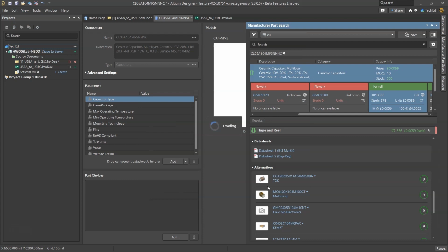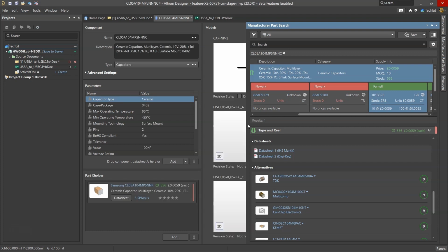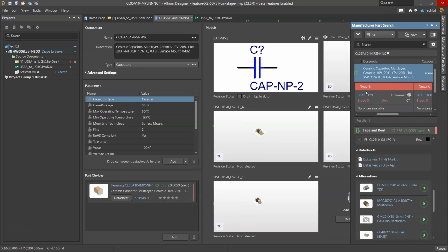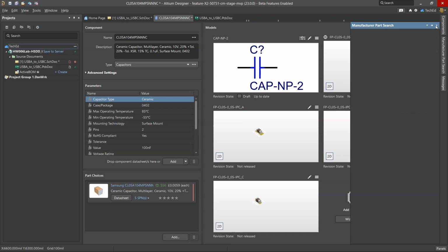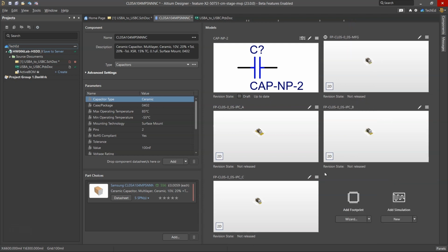Sometimes when you get problems in capacitor design and performance on your printed circuit board, it's due to say a capacitor that drops out a little too low and all that stuff. You want to have that data available to you up front, before you even get to the PCB layout phase, to see what simulation you can get done. That's a reason why I chose this chip, this USB 3.2 driver chip, because I can do some simulation.